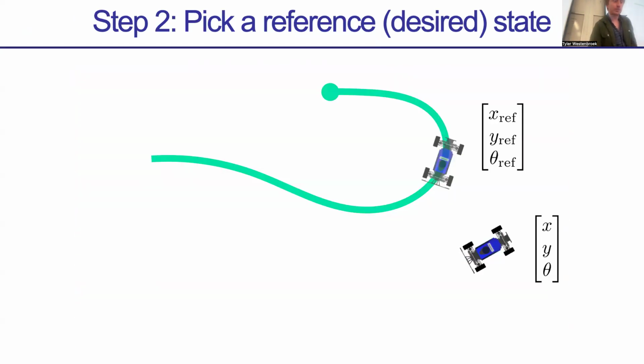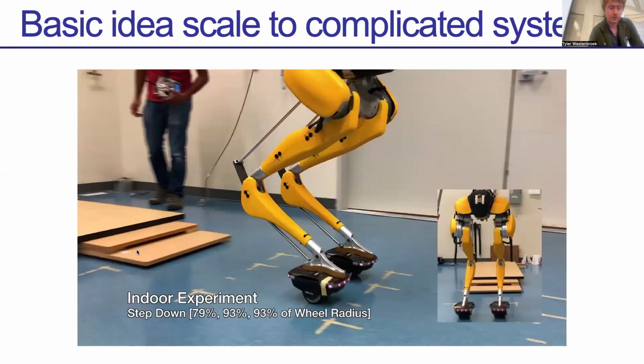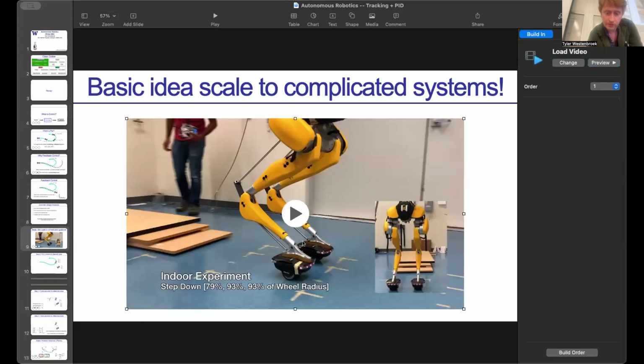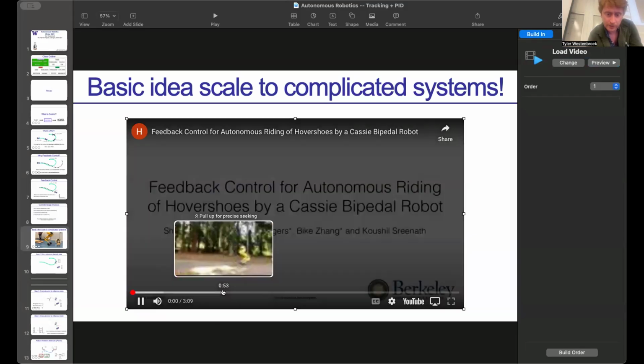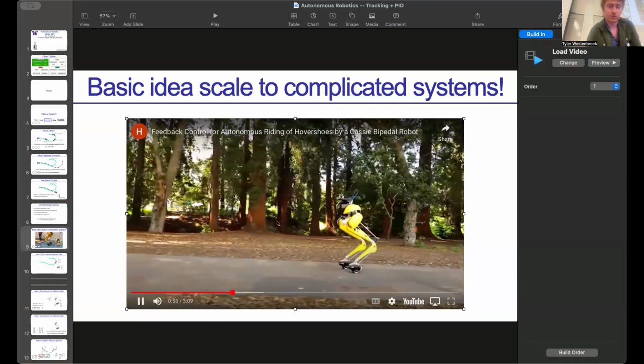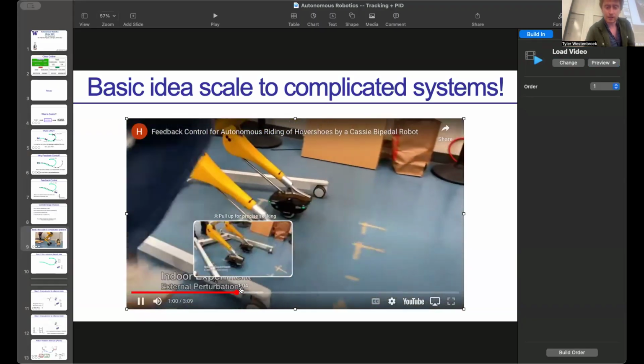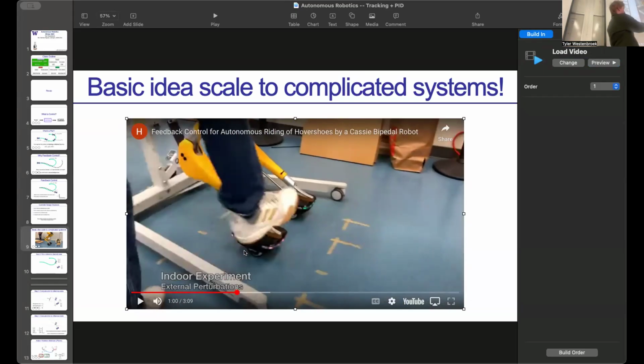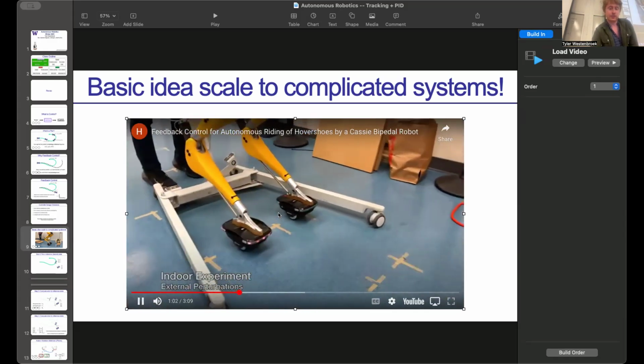So I actually just really quickly want to replay that last little bit right there, because I think it gives you a very good visceral understanding of what feedback control is. Okay, so up until this point where we have this disturbance, everything is going to plan, right? So our controller is doing great. And then this thing which I didn't plan for, my model, comes in, i.e. this foot came and kicks my robot off of its reference trajectory. And then what you're going to see is the feedback controller kick in and do its job.